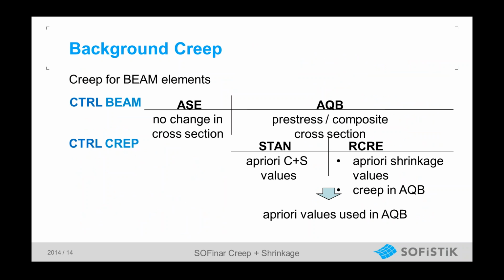Okay. Now I want to jump a little bit deeper in the background. So all I explained to you before was more or less the standard process: setting up your system, setting up your construction stages, defining creep and shrinkage with the standard settings, and simply analyzing it, and that's it. Now, to watch a little bit more in detail, I want to present this little slide.